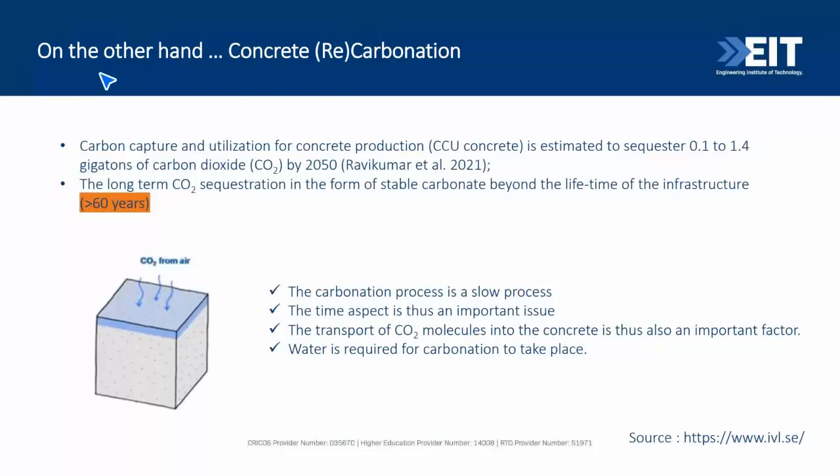So points to consider: we know that the carbonation process is a slow process. Time is an important aspect to have in mind. The transport of carbon dioxide molecules is also an important factor, just as Thomas mentioned, because it can also densify the cement matrix, so definitely can contribute to reduce concrete porosity, concrete permeability, and at the end of the day, improve concrete compressive strength.